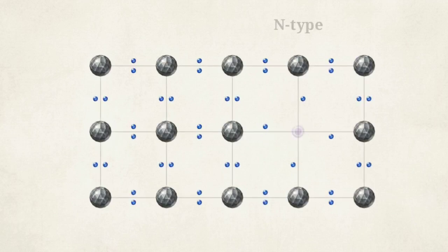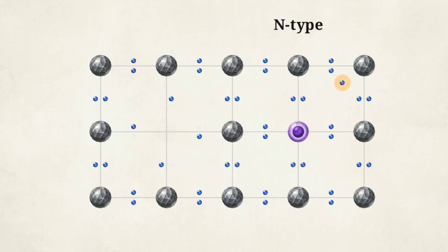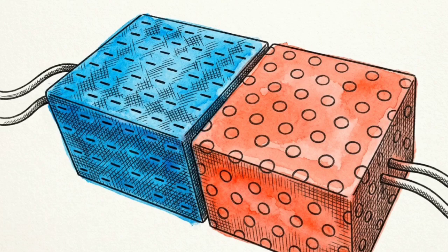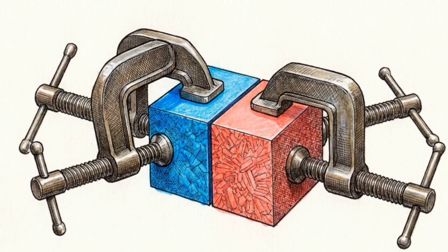In N-type doping, phosphorus adds 5 electrons, 4 form bonds, leaving the 5th unbonded and free. In P-type doping, aluminum brings only 3 electrons, leaving an empty void, a hole where a 4th should sit. We have now weaponized pure silicon into 2 highly unstable materials. The N-type is packed with excess free electrons, and the P-type is riddled with empty holes desperately seeking electrons to fill them. The real physics begin when we physically press these 2 engineered materials together.